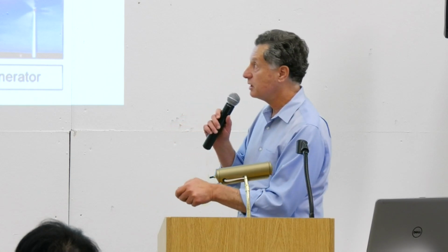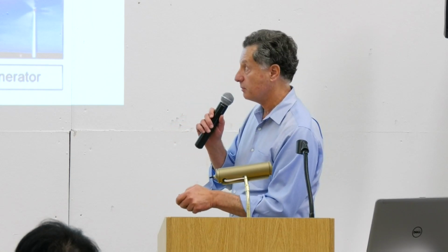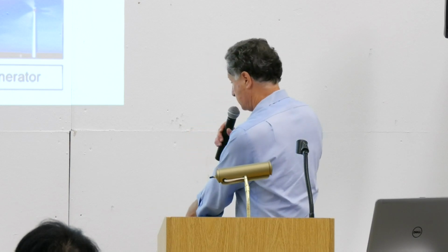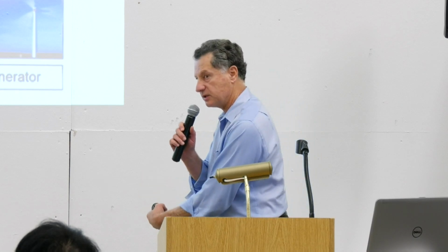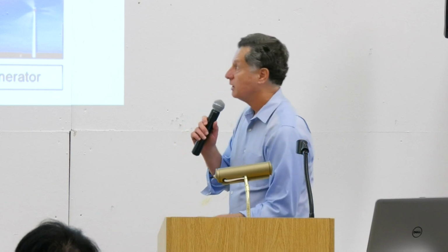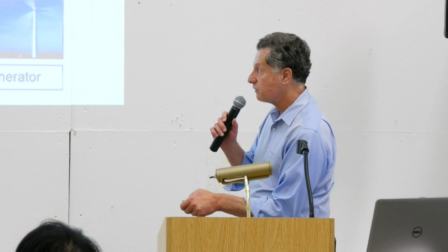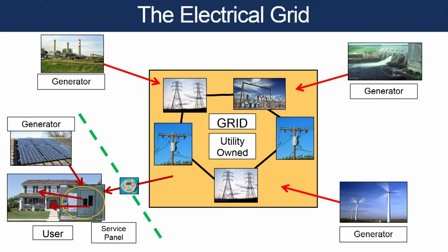So this is generating electricity as much as it can, as much as the sun goes up. Now electricity doesn't flow until there's a draw. The energy is sort of sitting there waiting until you have a draw, then it flows. So if you have a draw here, whatever energy this produces goes right to satisfy your home first. If there is a surplus, it will automatically flow this way back into the grid because all this is wired together. And as soon as it crosses this line and flows this way, this meter will pick it up and it will credit your account in a certain way.